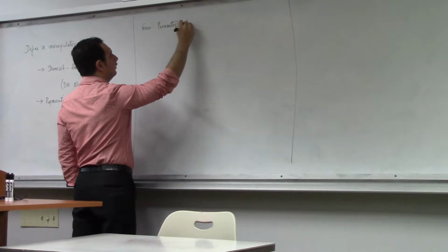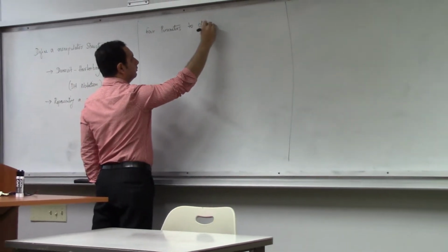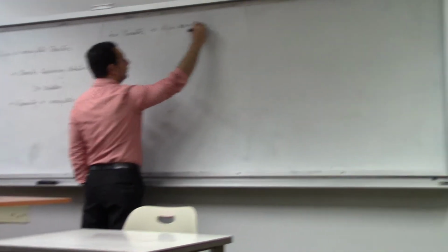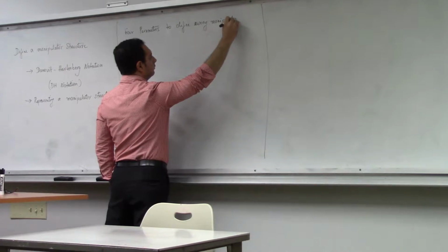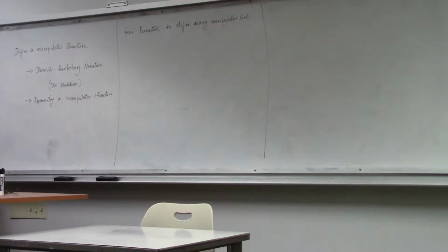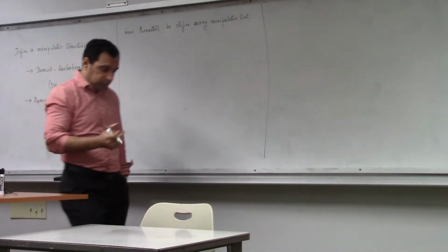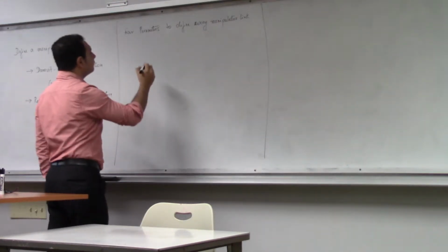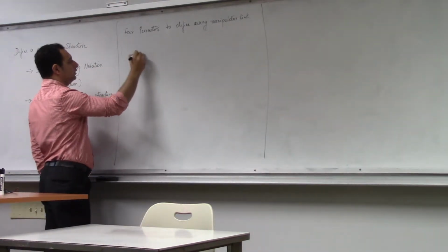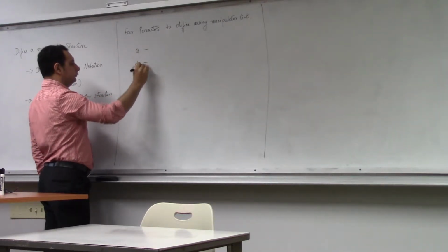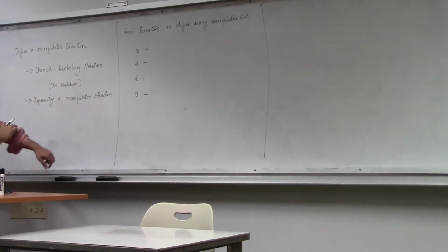The reason we need 4 parameters is because we want to build a transform for a link. The 4 parameters are a, alpha, d, theta. Every link is defined by 4 parameters.